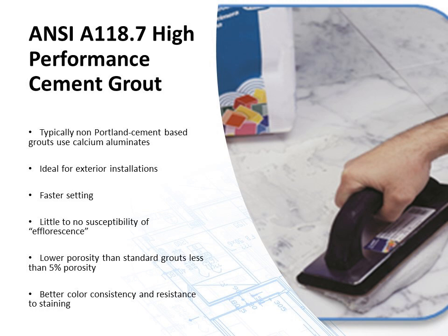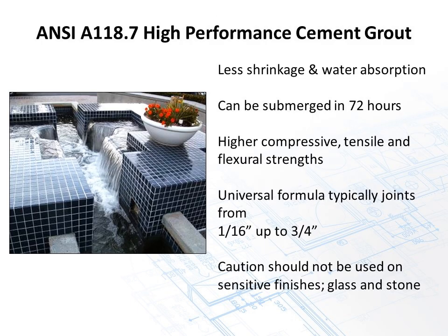I will say that if not properly weatherproofed, etc., and efflorescence is generated by the setting material or the substrate, it still can come through even the high-performance grouts. Lower porosity than standard grouts, less than 5% porosity, and better color consistency and resistance to staining. An ideal choice for exteriors.